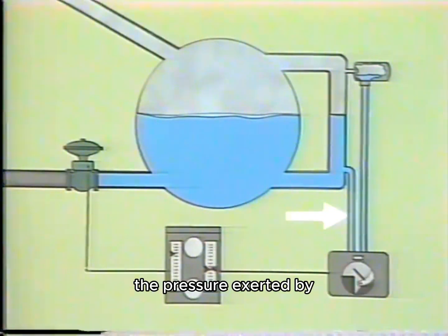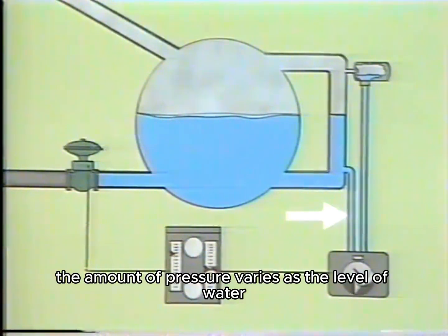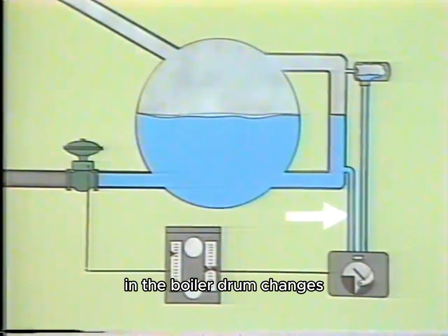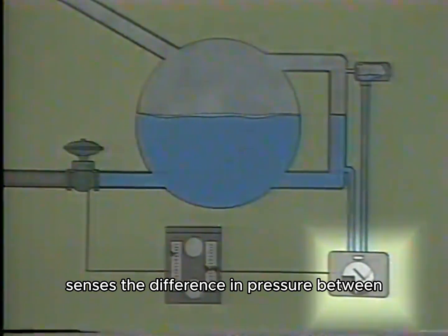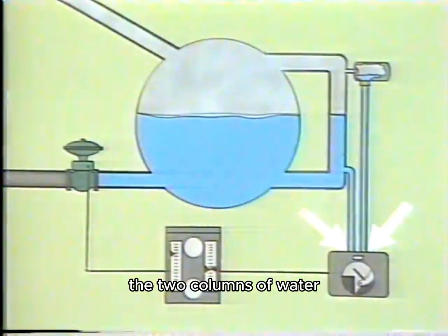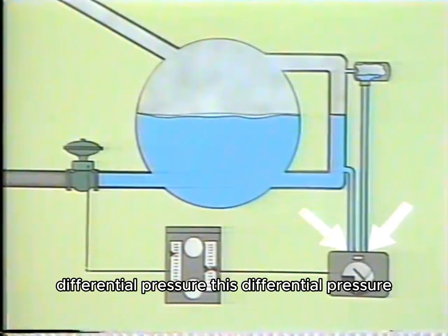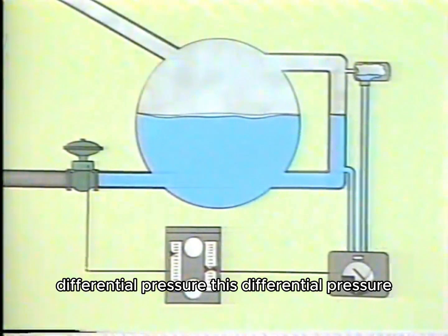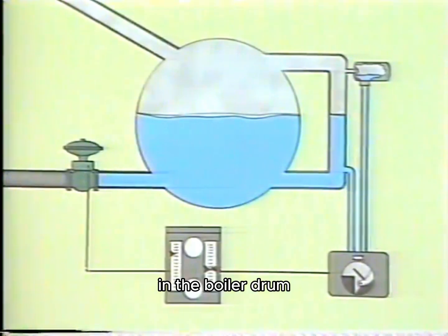The pressure exerted by the column of water in this tube is variable. The amount of pressure varies as the level of water in the boiler drum changes. The primary element in the transmitter senses the difference in pressure between the two columns of water. This difference in pressure is called differential pressure. This differential pressure is an indication of the actual water level in the boiler drum.